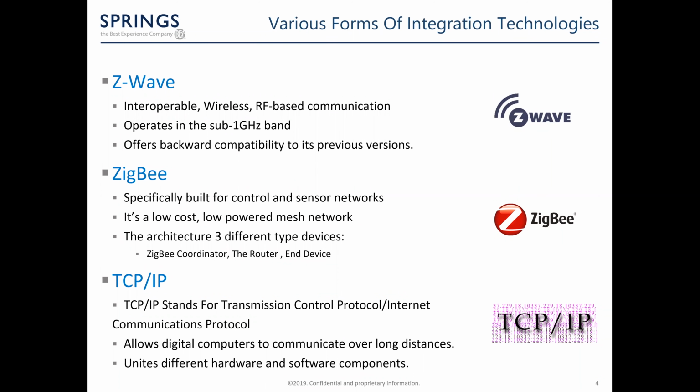The communication system is less expensive, and some may say easier to network, versus other proprietary short-range wireless sensor networks such as Bluetooth and Wi-Fi. Zigbee systems consist of 3 different types of devices: a Zigbee coordinator, a router, and an end device. Each Zigbee network must consist of at least one coordinator, which acts as the root and bridge of the network.